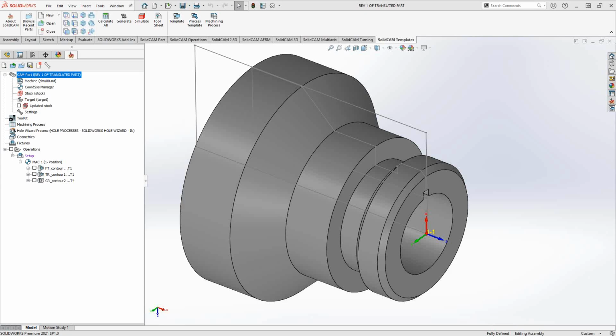And that is actually what we're associated with. So if you're doing configurations, as long as you change a dimension but keep that same face, same ID number, we're associated with that. Your original SolidWorks model becomes your design model, but it still has all the same ID numbers, so that when you make a change on the original model, your SolidCAM copy of it, design model, updates as well. So all of that is the associativity coming into play.